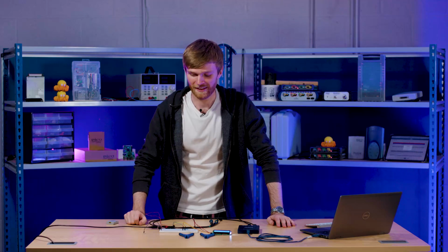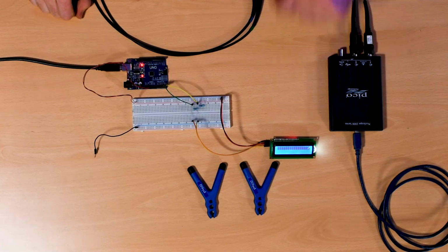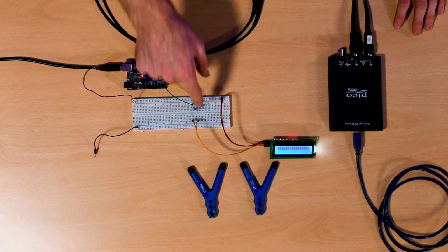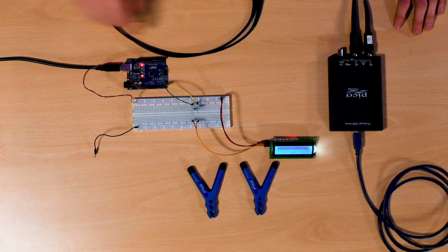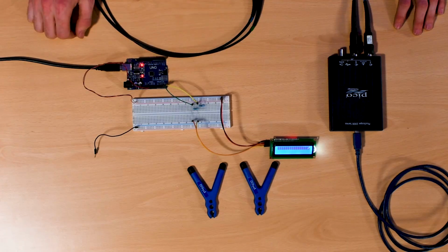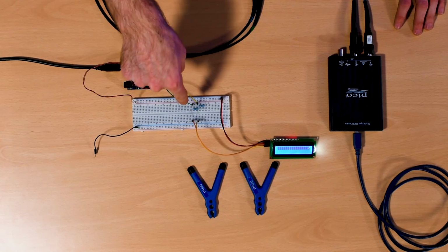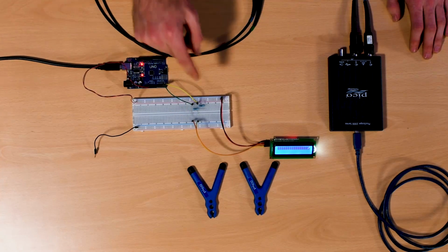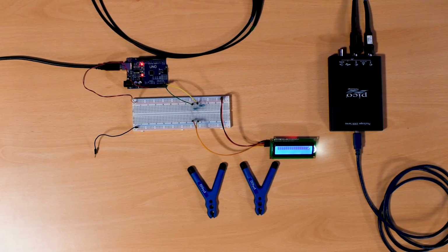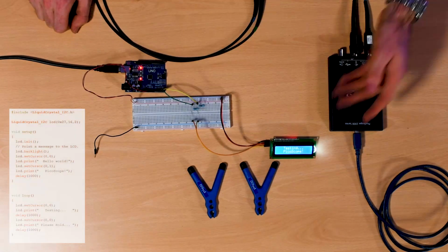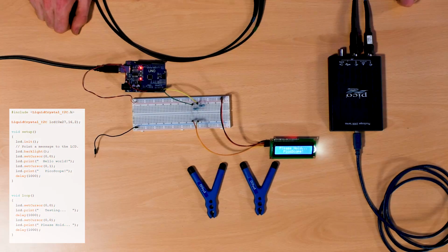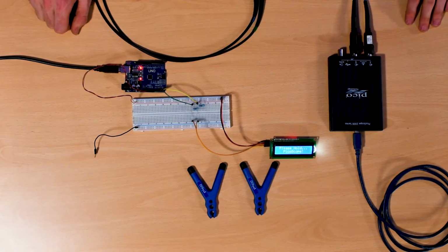So what we have here is we've got our Arduino and our LCD, and they're both powered by the Arduino. So with the I2C, we've got two 4.7Ks, which are pulling these two SDA and SCL lines high. So the green and the orange is the SDA for continuity, and the yellow is SCL. On the Arduino, we have a simple script which is just going through some quick messages, sending them to the I2C on the back and populating it onto the front of the LCD.